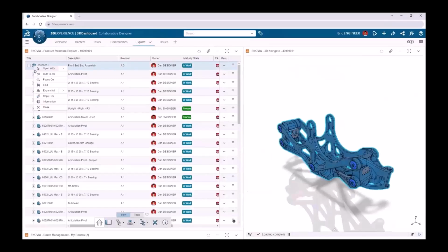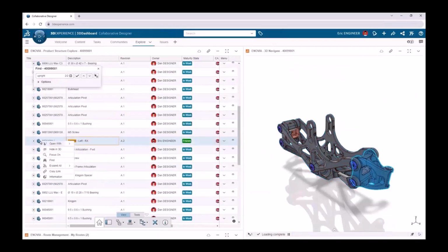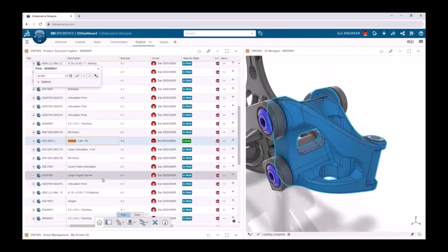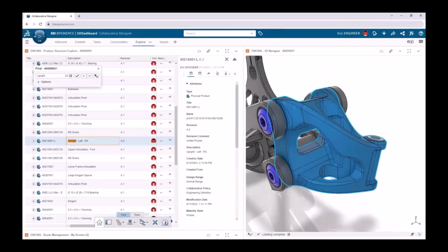You can also display the structure of your assembly from a browser. So I can display my assembly without having SolidWorks, and I can show it to others. And then there are these two applications that side by side show the assembly structure and then the parts. The parts highlight when you click on them on the tree. And then you can see information like the properties. So what is the material? What is the item number? Who created it? When?